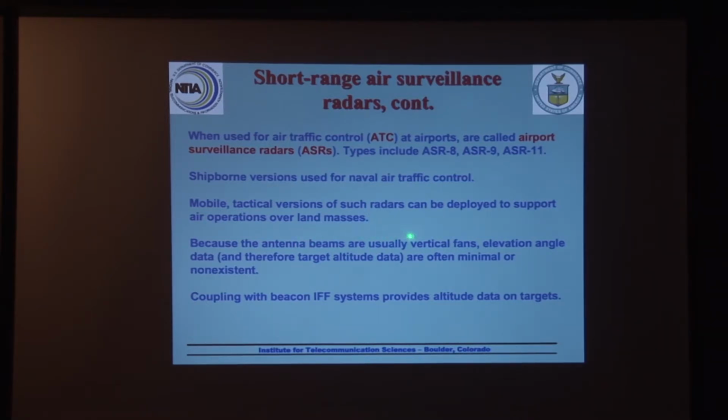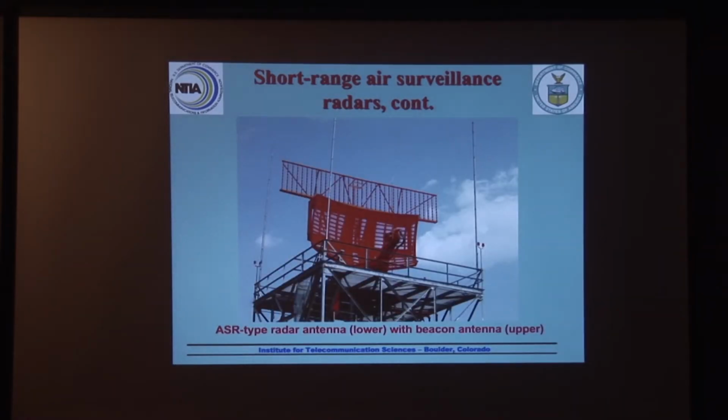Because the antenna beams on these are usually vertical fans, remember, you generally don't get elevation angle data, and therefore you don't generally get target altitude data. Or in some cases you get some minimal information. So it is important, if you've got cooperative targets, to get them to operate with beacons. Otherwise you have to take other measures to try to get altitudes.